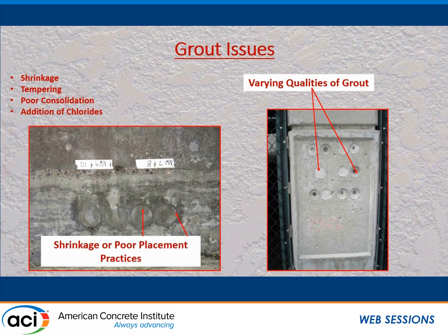We have a job now, a 2-year project where we're opening up thousands of pockets to trim the tails. You'll do 10 pockets and it's probably 10,000 PSI grout, harder than heck to get out, and you move over 5 more pockets and the stuff crumbles out. There's just no consistency, so if you're trying to bid this, it's really difficult to give a hard number, because you just don't know. If it's 10,000 pound grout and you're trying to carefully excavate it, that's difficult to do without doing additional damage.